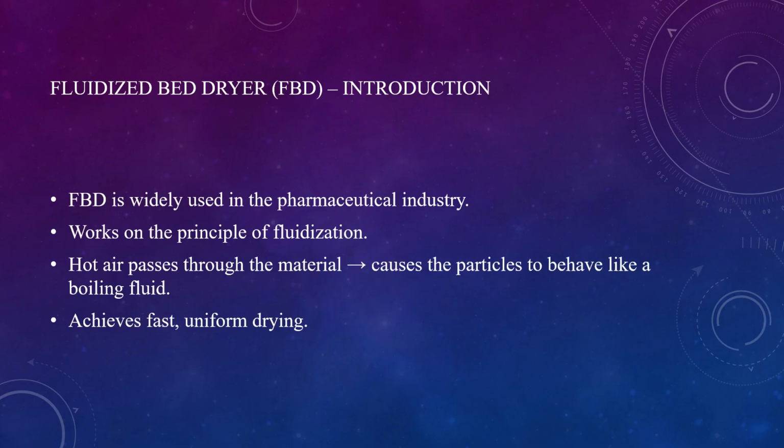Now let us move on to one of the most commonly used dryers, the fluidized bed dryer. The fluidized bed dryer, also known as FBD, is widely used in the pharmaceutical industry because it dries material quickly and uniformly. It works on the principle of fluidization, where hot air lifts the solid particles and makes them behave like a boiling fluid. This ensures that every particle receives equal exposure to heat.